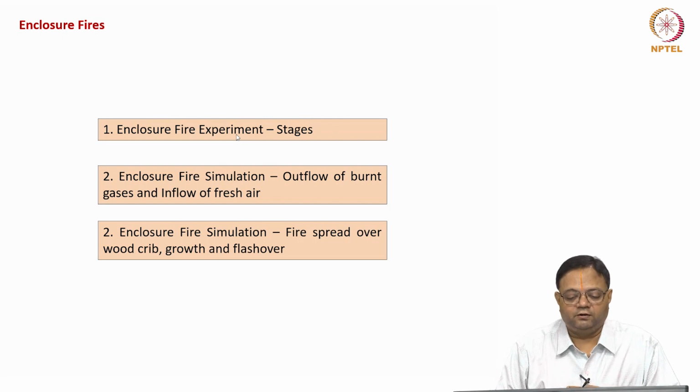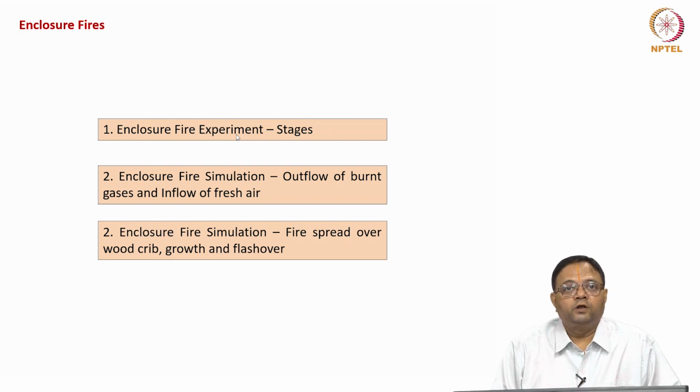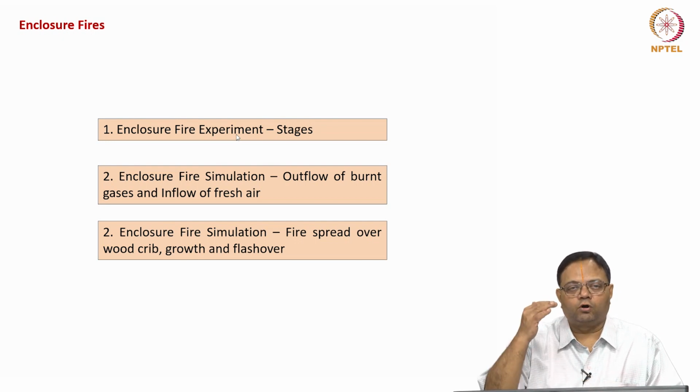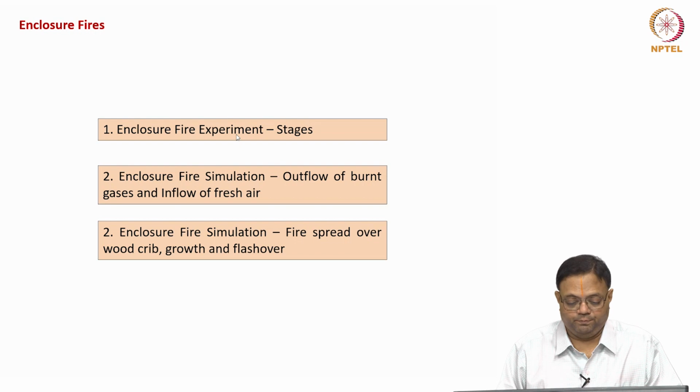Then the second case is done using a software called Fire Dynamics Simulator. Here the enclosure fire sourced by a liquid fuel methanol pool is used, where it is clearly shown that after the fire develops, how the flow goes out of the compartment and the air comes into the compartment, etc. And the smoke layer height also is shown as a function of time.